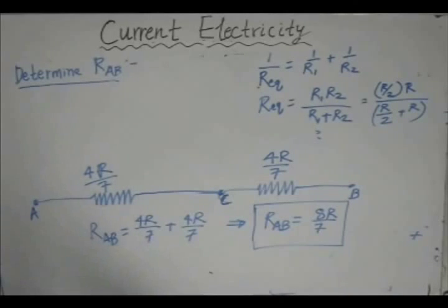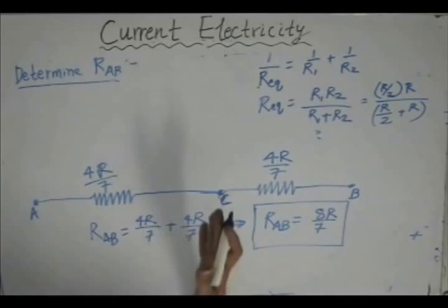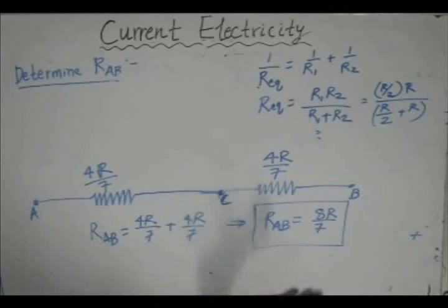So this is how we can say that even though the circuit was initially neither in series nor in parallel, after some modifications, as in this case for the symmetrical plane, we got the resistors in series and parallel combinations. In this manner, we can reduce any complex circuitry into very simple circuitry containing series and parallel combinations of resistors.